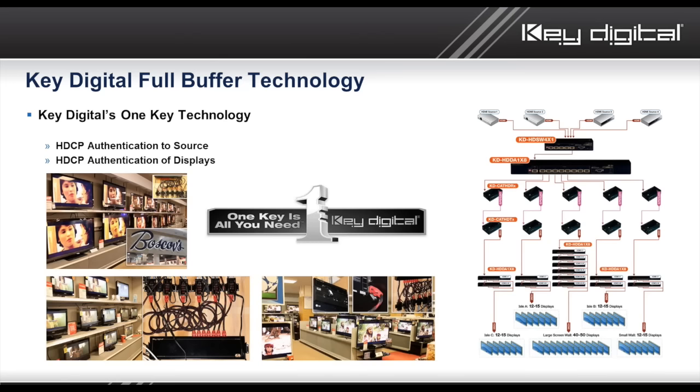In other words, if you use a black box, let's just call it the dirty word, a splitter, and that splitter doesn't manage HDCP properly, well, your HDCP encrypted source content will see, oh, there are 8 displays viewing me right now, and if that source doesn't have 8 keys, which cost money, folks, you will not get a picture on all 8 displays.